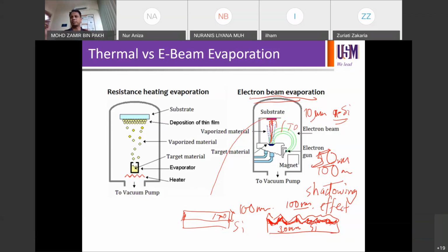But as far as planar substrates are concerned, usually it will not be that critical because you get to rotate your samples during deposition, so the samples will experience rather uniform coating during the process, so it's not a big deal. But for textured substrates, even though you do rotation, you will still experience some problems due to the shadowing effect.